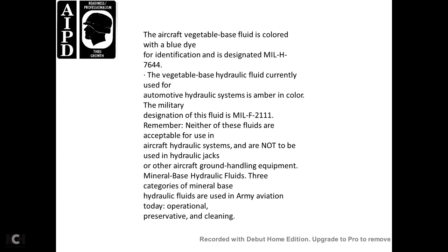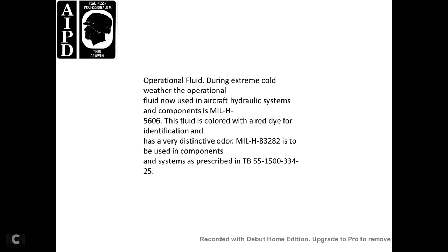Mineral-based hydraulic fluids. Three categories of mineral-based hydraulic fluids are used in Army aviation today: operational, preservative, and cleaning. Operational fluid for extreme cold weather operation of the aircraft hydraulic system and components is MIL-H-5606. This fluid is colored with red dye for identification, a very distinct color. MIL-H-83282 is to be used in components and systems prescribed in Technical Bulletin